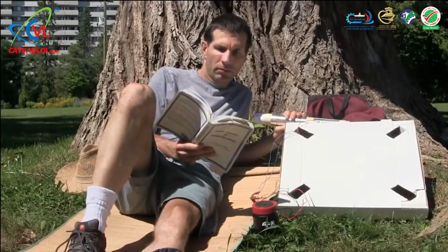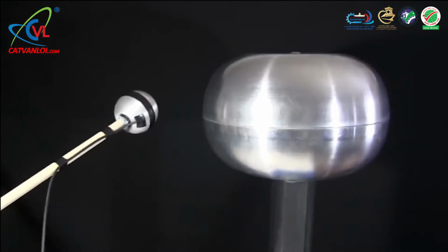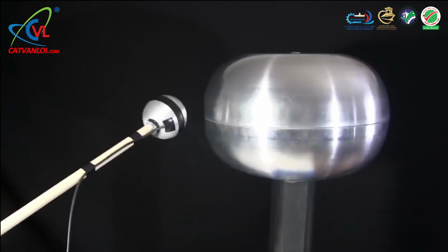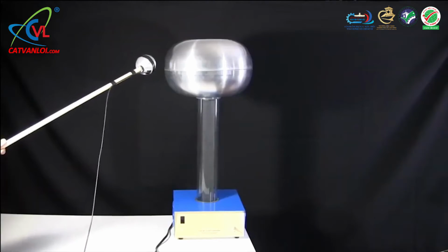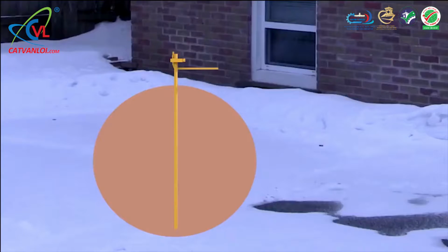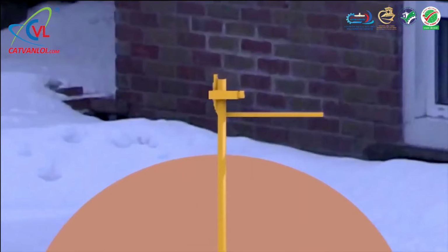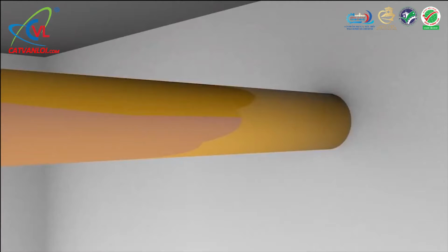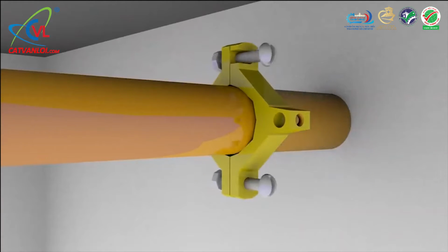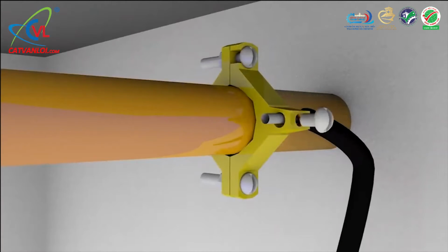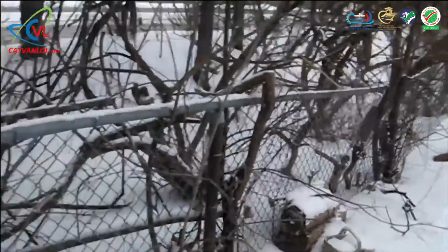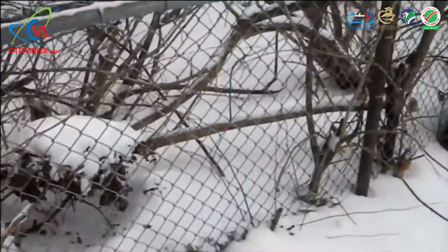Here, I'm the ground. Often when playing with high voltage, you'll have a ball connected to a wire going to ground, and make a spark by bringing that near a charged object, like this Van de Graaff generator. A fairly safe way to ground that, if you don't have a ground rod that you can connect to directly, is to find a metal pipe that you're certain goes into the ground, like this copper cold water intake pipe from the city, or this metal fence would do, since it makes plenty of contact.